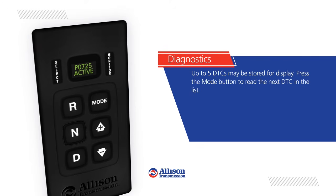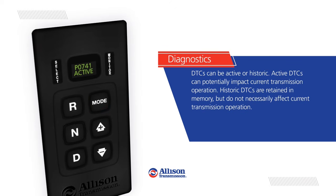Up to 5 DTCs may be stored for display. Press the Mode button to read the next DTC in the list. DTCs can be active or historic. Active DTCs can potentially impact current transmission operation. Historic DTCs are retained in memory, but do not necessarily affect current transmission operation.